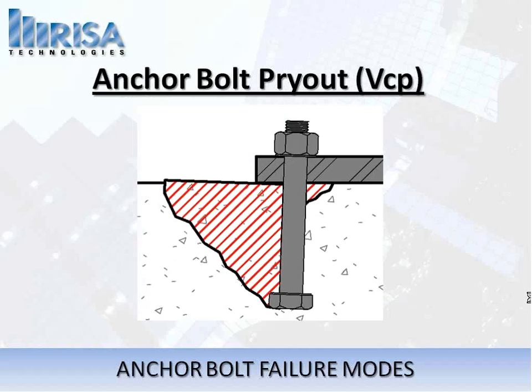And in this case, the anchor bolt is actually capable of rotating because a slip plane forms when you get a shear rupture in the concrete, and that triangle of concrete you see on the left is able to pretty much push itself up and out, and the bolt's able to almost flip over on itself. And so that's another failure mode that is definitely something to consider. And one of the nice things is that RISABase automatically is going to check all these failure modes for you, regardless of whether or not they govern, will determine whether they govern and will determine what the capacity is for each one of these modes.